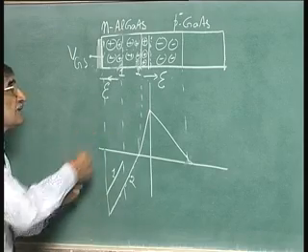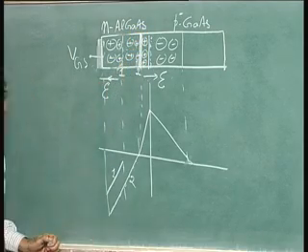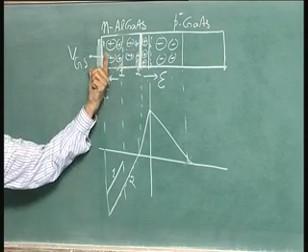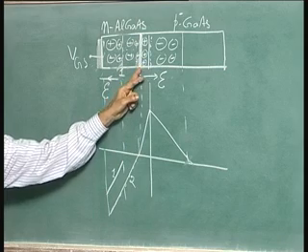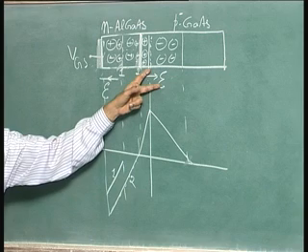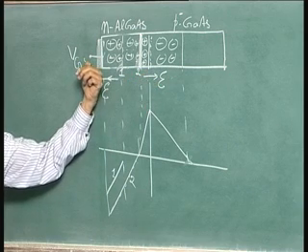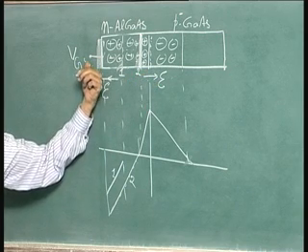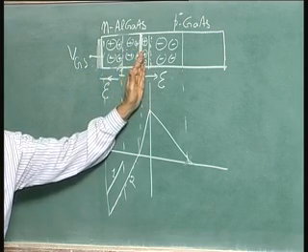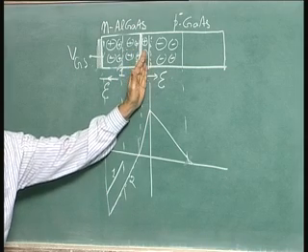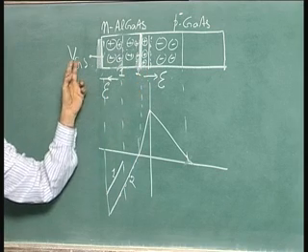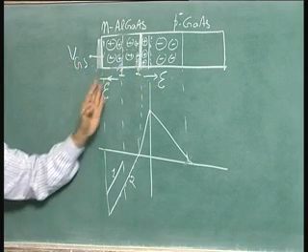See, here up to this point, all these are plus. All these charges belong to this Schottky, and the charges beyond this point 2 belong to this p-n junction. Now, if this Schottky barrier needs more positive charges, the only way it can happen is by the depletion layer of the Schottky barrier encroaching into this region. It moves into this region. That means some of the positive charges from here participate in the Schottky barrier. Okay. What happens to the depletion layer here then?